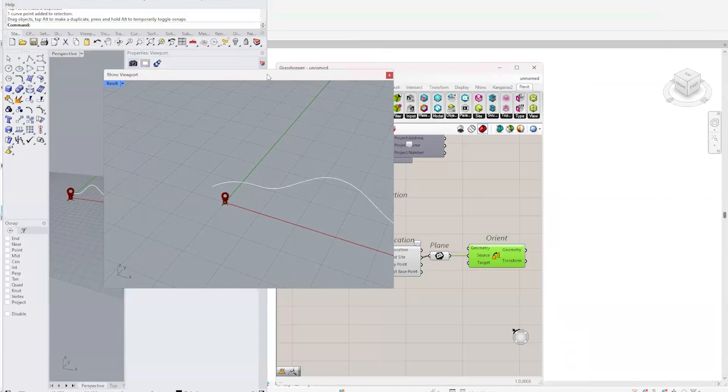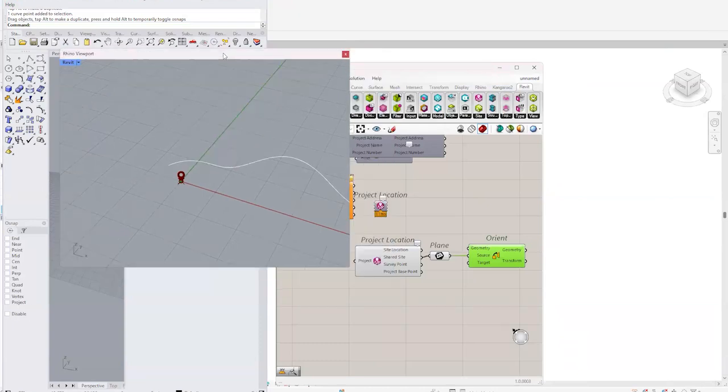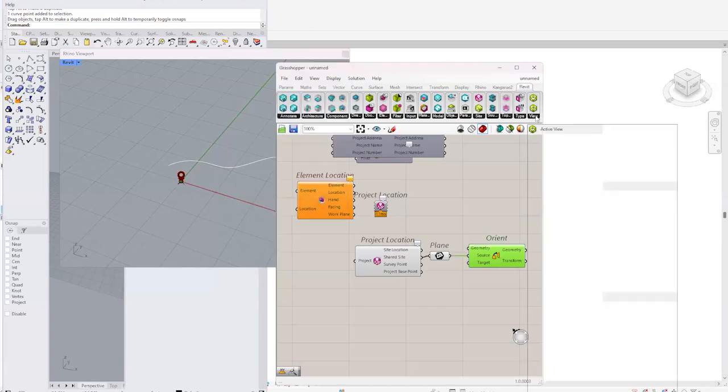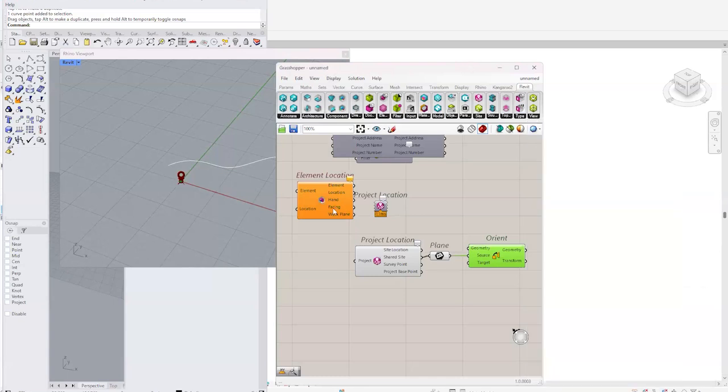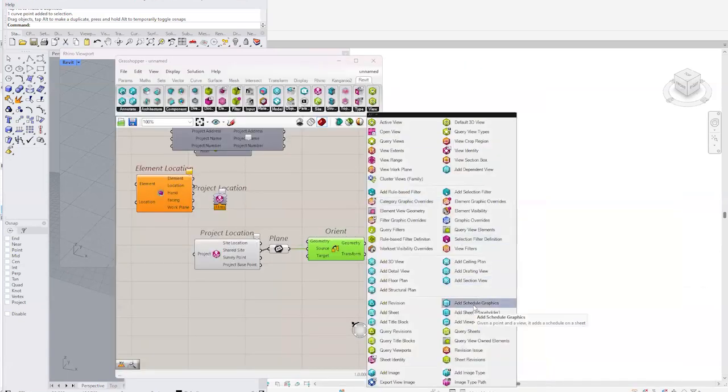Great. And there's another question from Philip. Can we create Revit schedules with those panels created from Rhino? I think this is one of your example files. Can you create the schedule? Yep. They're going to be shared parameters. This add schedule component is only adding an already created schedule, the schedule graphic, onto a sheet. We do not have